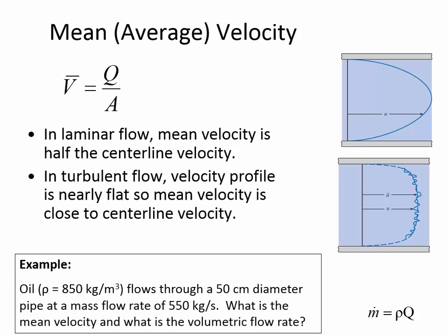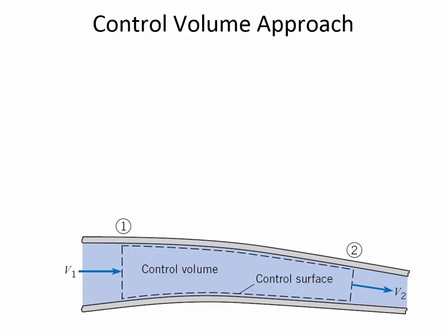All right, any questions about this example? The control volume approach is the idea of keeping track of fluids and where they are and where they're changing position over time. So what this is showing is a pipe that has a changing diameter and the flow has a changing direction. There's nothing special about this device other than to emphasize applying the control volume approach and the thinking behind it. The flow doesn't have to be uniform.